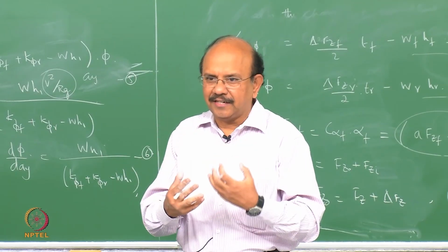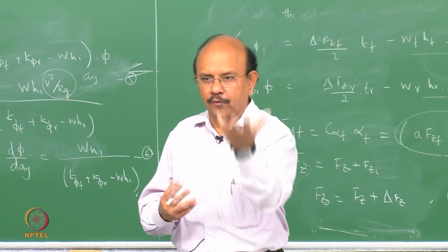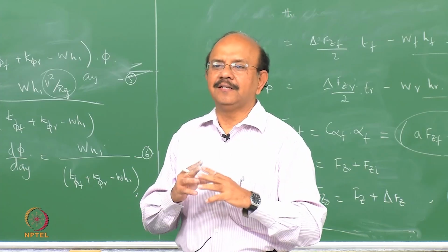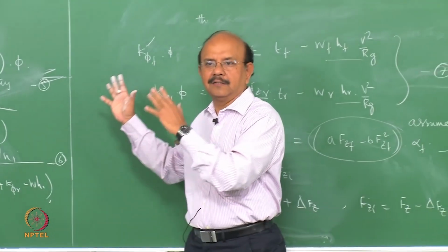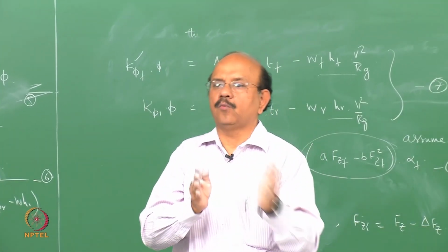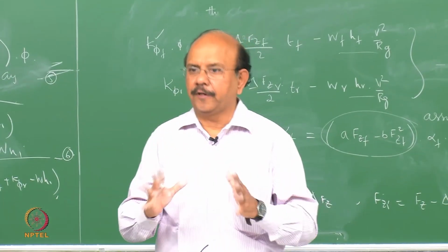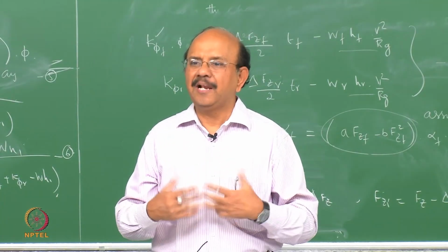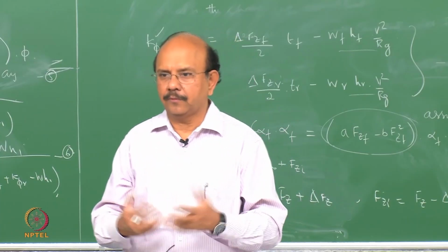The advantage is that we can look at it very easily and tell what would be the effect of roll. The disadvantage is that it has its limitation of having only one tire, a bulk quantity, at the front and one tire at the rear. So this is a very simplified model, the bicycle model, but it helps us to understand what happens when there's a roll transfer.